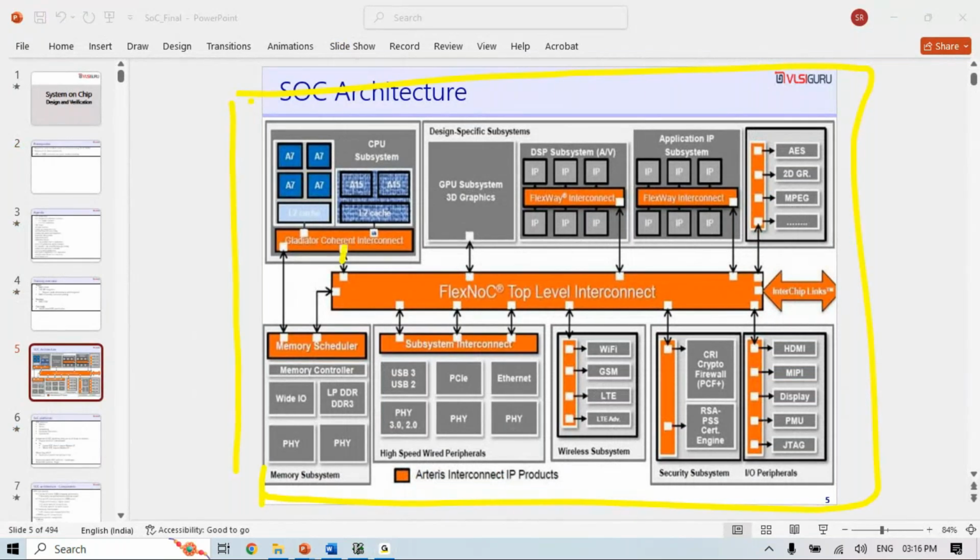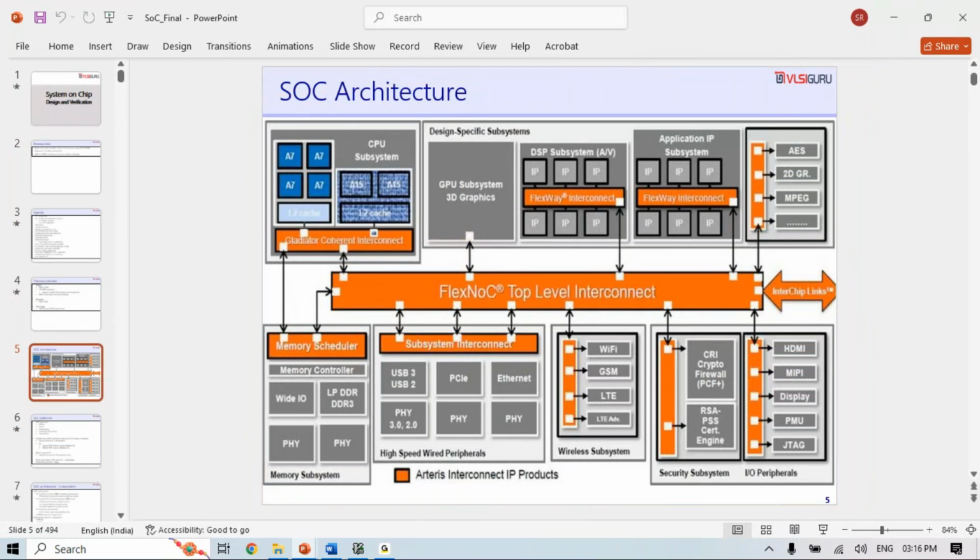The only thing we are doing here is that, instead of putting everything onto a single chip and connecting them through some PCI Express link, where you are able to send CXL traffic from here to here, we are manufacturing them as separate chiplets. We are adding additional layers like the die to die adapter and physical layer, where we convert that CXL traffic into something called UCIe format. There is a small transformation that happens. Then that will be transmitted through the link to the other one.